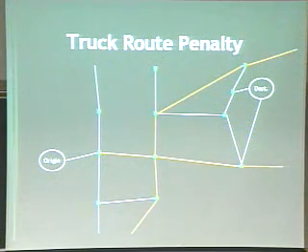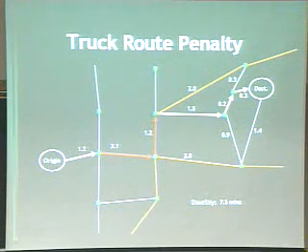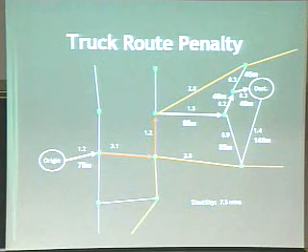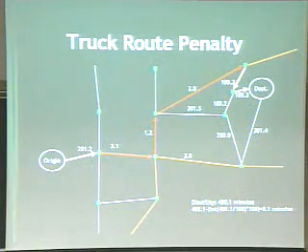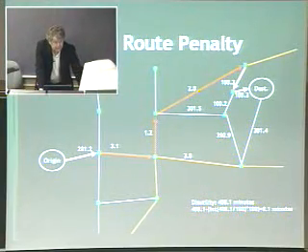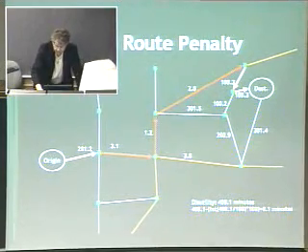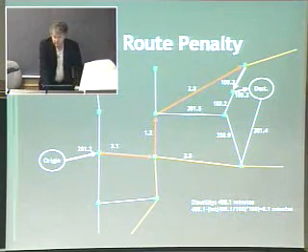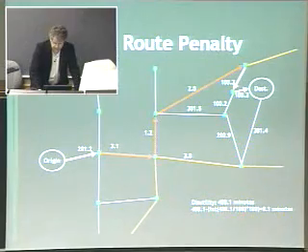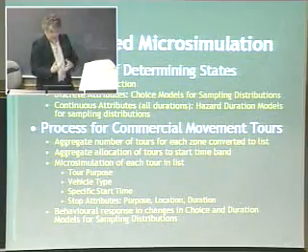So just an illustration of that, if I have an origin to destination that I'm considering alternative routes for, and those are the truck routes in orange where drivers are permitted to drive as much as they want, but they must minimize their distance on the other links. If we had those particular disutility values and we allowed just a standard minimum path process to work without the penalties, they would end up driving in the pink parts far more than they should at the destination end. So what we had to do was have in addition the lengths of those links, and then on that basis put penalties of additional 100 minutes for each 50 meters or portions thereof, and then have the assignment algorithm do the minimum path through that, and it would come up then with the legally appropriate route assignment on the destination end. But then after we're done with that, we can then strip out using the formula shown at the bottom, and we come up with the 8.1 minutes of disutility is the actual time that they would suffer on the network. So we had to build that up and get that working, and that does work fairly well.